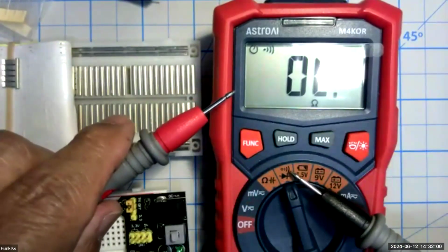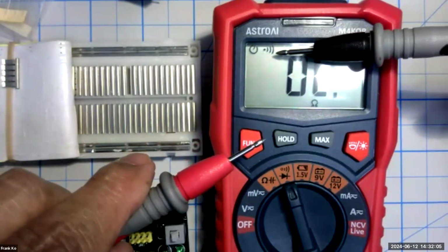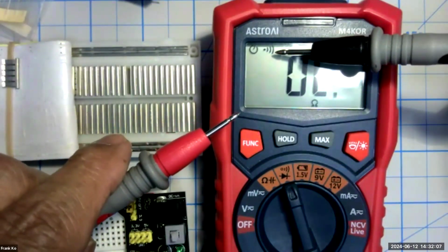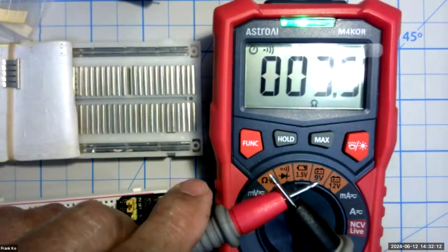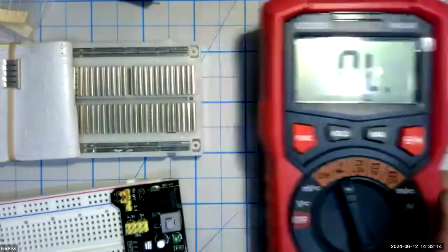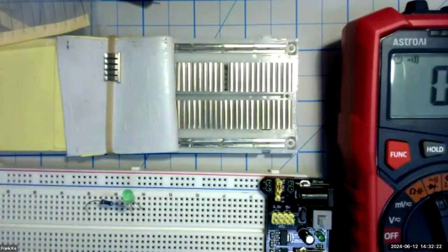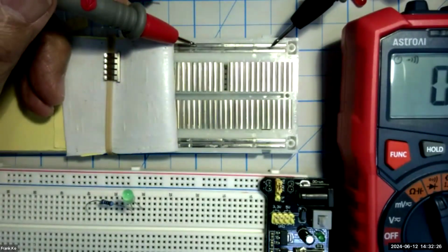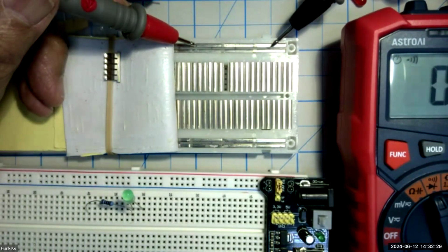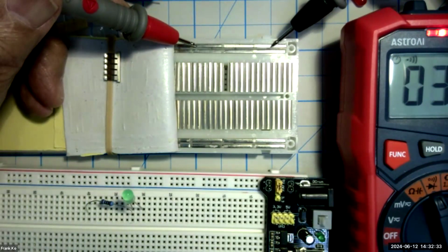So that's what the display is showing us. So this is the continuity test mode, the one with the little speaker symbol. The little LCD display screen shows we're in the continuity mode because it's showing the symbol up there, and touch continuity. Now, we're going to do this on the board also and demonstrate from the underside why we have continuity. And that is if I go to touch here and here, listen carefully. My hands are shaking. There we go.